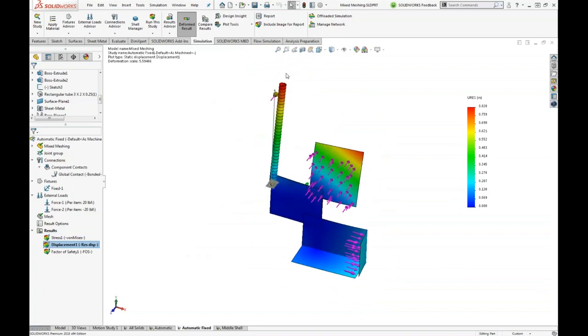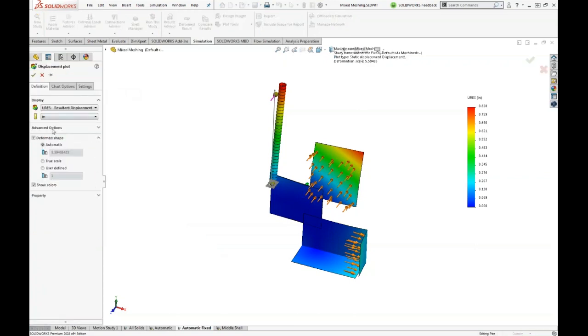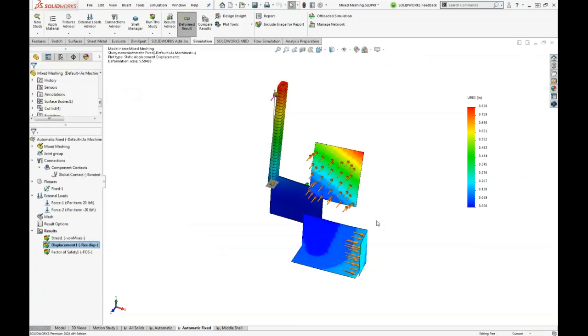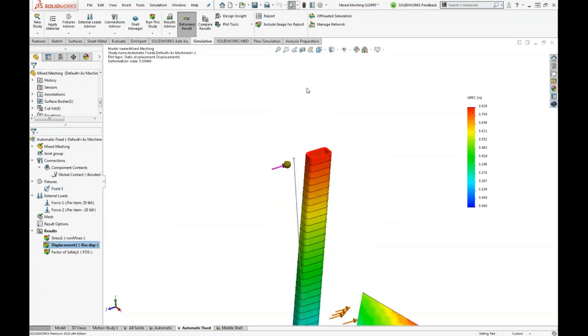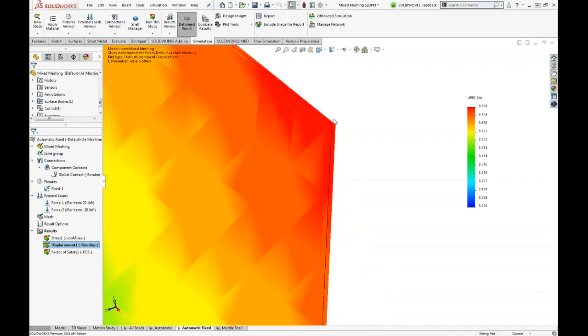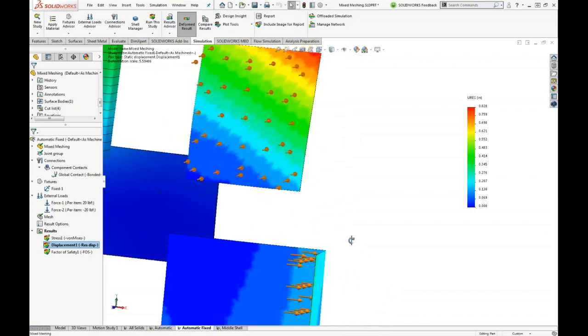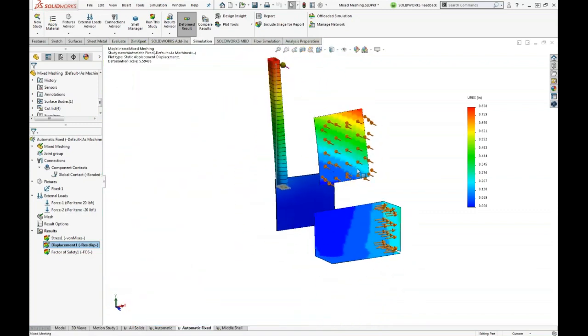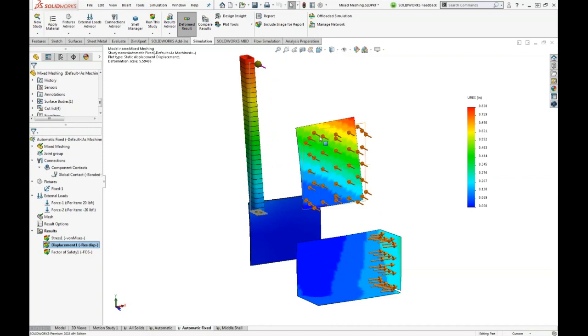One of the downsides in shells and beams is that you've got these simplified representations of the geometry. But a few years ago, we got a switch to map the stress and displacement results to a representation of the real geometry. And so these things now have a thickness, and that can be better for communicating your result. But I would say to always review your model for things that are shells, thin, constant thickness, put a shell on that, and you'll see big improvements in performance and often in accuracy as well.